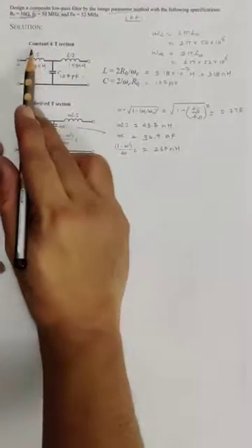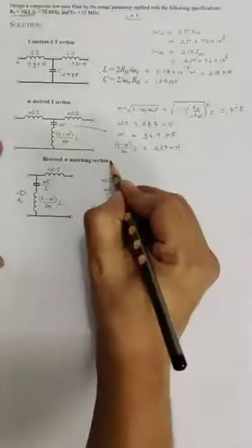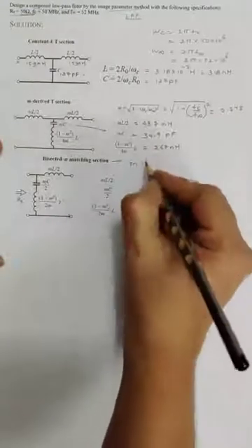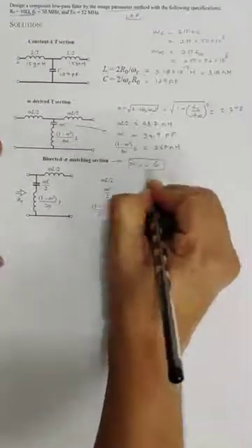So after constant K and M derived, at the input and output side, we require bisected pi matching section, and for designing this one it is fixed that m has to be 0.6.